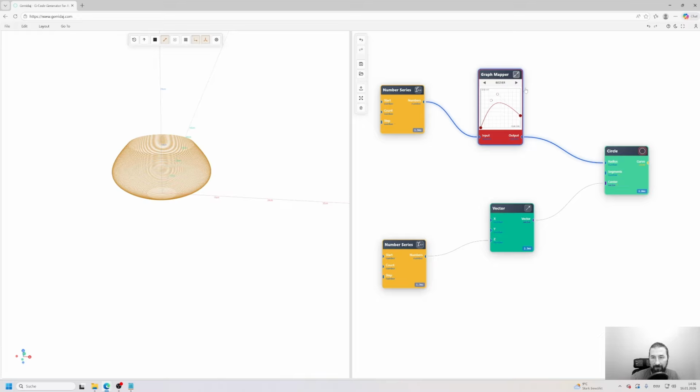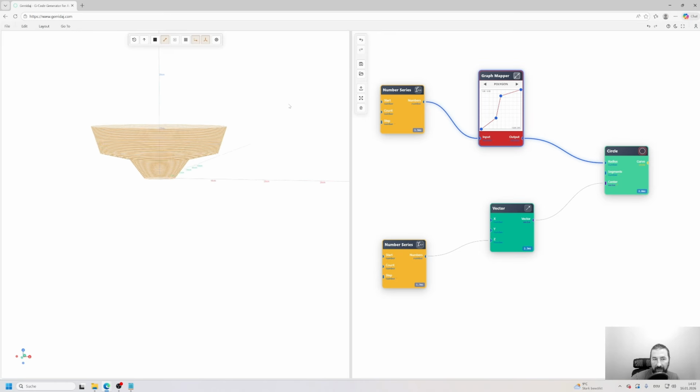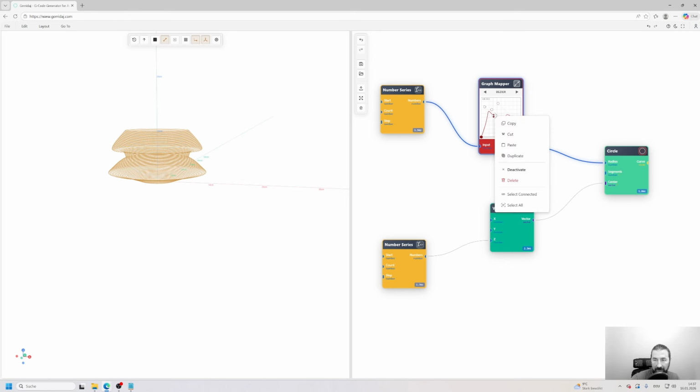You have here different functions which you can use for the mapping. So Bezier is a very powerful one because you can define the shape in a very natural and intuitive way here. But you can also use polygon here. If you hold down the Control key and press the left mouse button here, it will add a new point, and you can add as many of them as you want and create shapes with sharp transitions. So Bezier gives you smooth transitions, but you can also have sharp transitions with the polygon. Actually, you can also add points in the Bezier in the same way. Just hold down the Ctrl key and press the left mouse button, then it will add some new points. There's actually a way to remove them somehow.